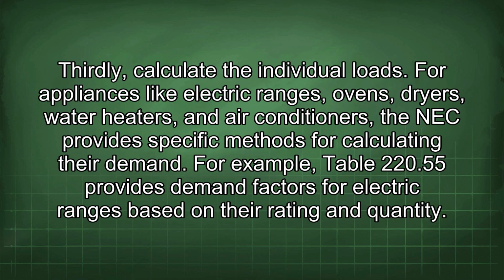Thirdly, calculate the individual loads. For appliances like electric ranges, ovens, dryers, water heaters, and air conditioners, the NEC provides specific methods for calculating their demand. For example, Table 220.55 provides demand factors for electric ranges based on their rating and quantity.